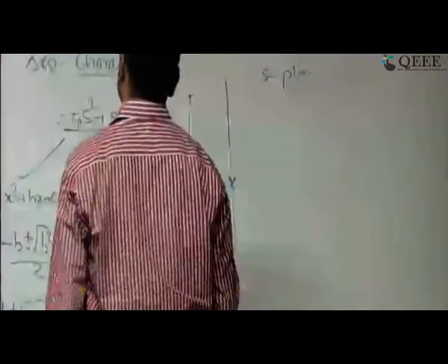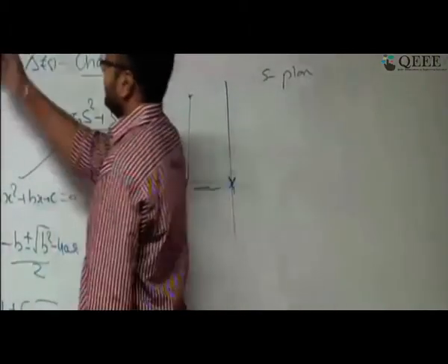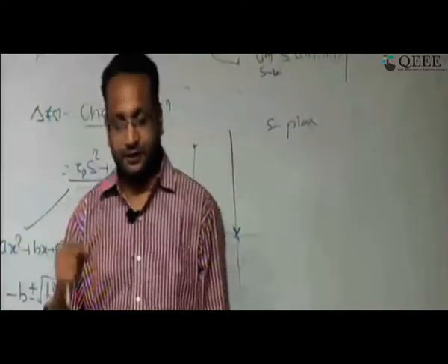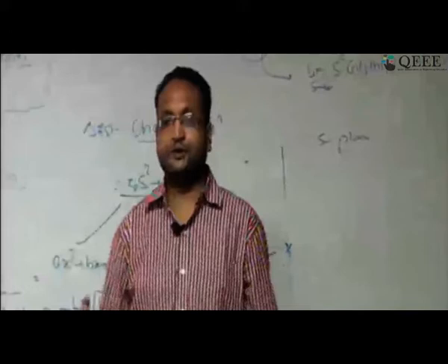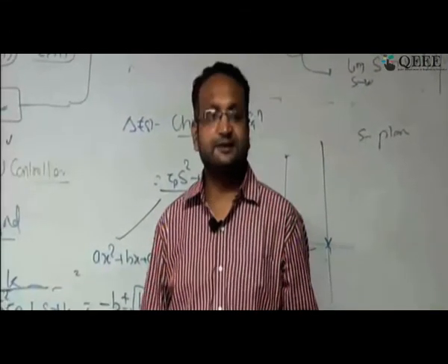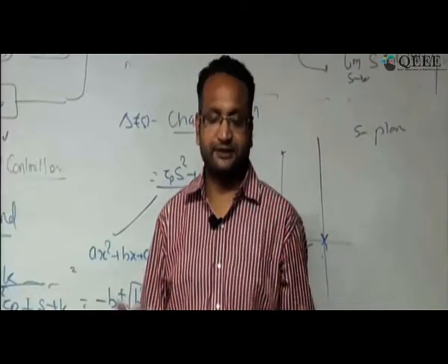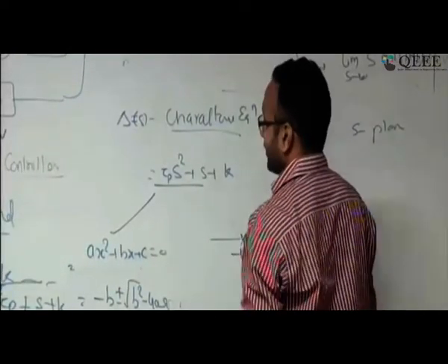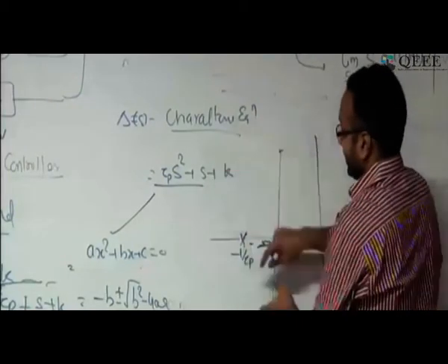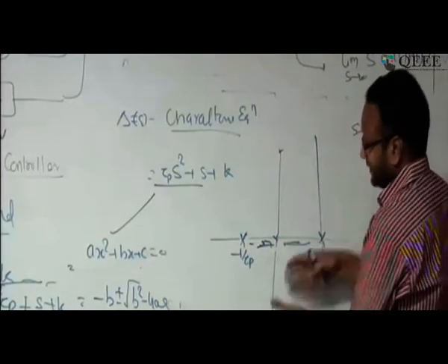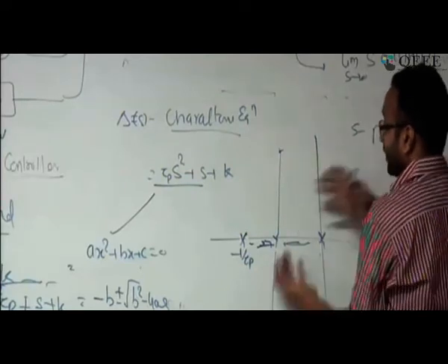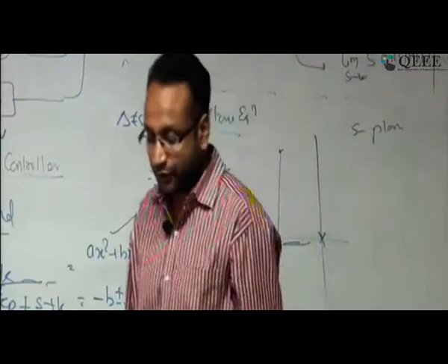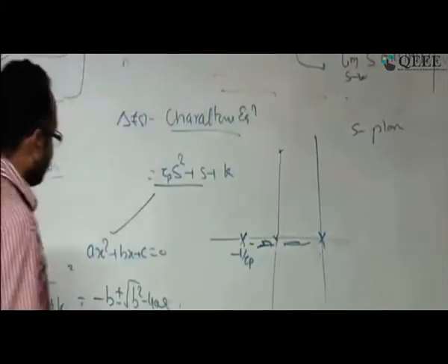And one more part which we have discussed earlier also, because in this case, in the analysis I have done, I have assumed that my amplifier, controlling the offset, or transducer, is a zero order system. In practice, it's not going to be a zero order system. There's going to be some first order or second order system. The entire system is going to be very high order. And if I have a very high order system, if you keep increasing the constant, there is a chance the pole of the system might go to the right half plane, and your system becomes unstable. Okay. So these two parts are clear to all of you.